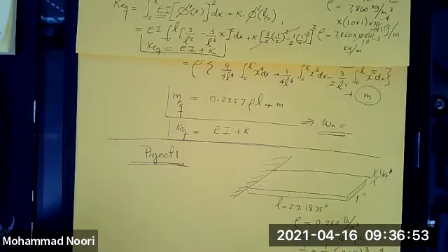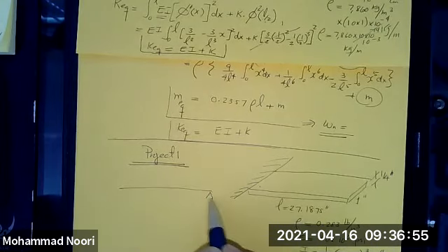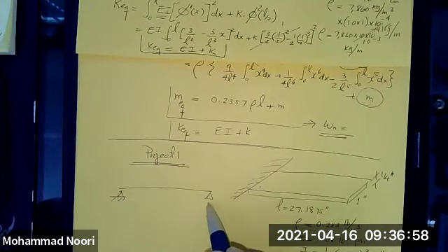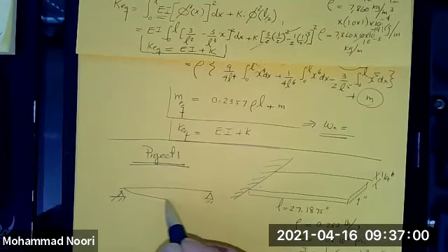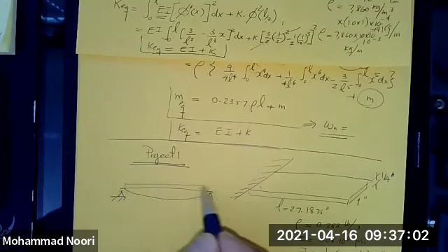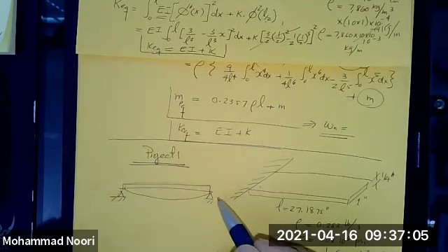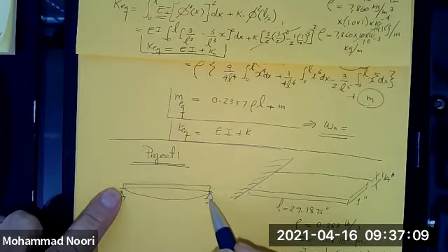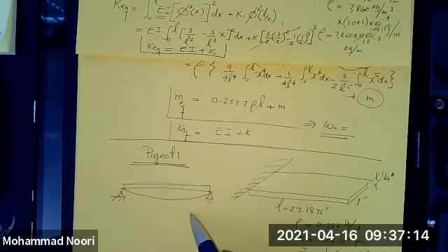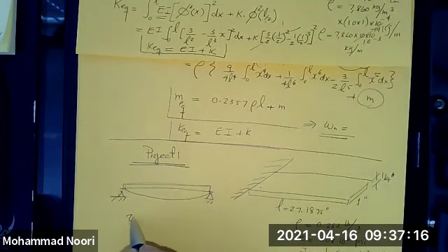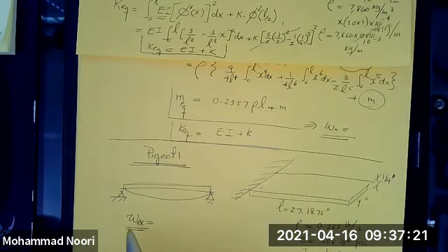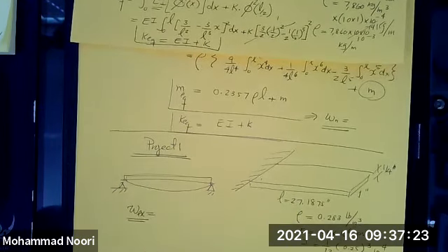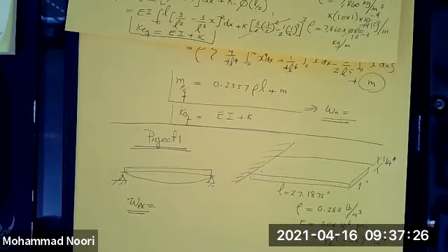Consider a beam like this, or you can consider some simple case, like a cantilever beam. Put that ruler and bolt it here, not clamp, because you want to have rotation allowed. And then do this. Use the exact formula, which I will give you, and I will discuss it right now.